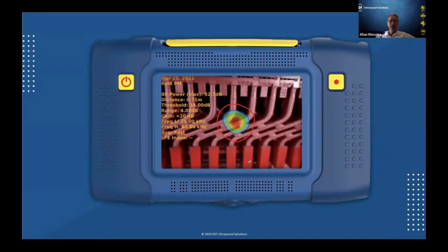There's a slide here that shows what the defect was. In behind there, they found a welding rod. During the rebuilding of this asset, one of the welders had carelessly discarded a welding rod, and it was caught in back, and it was bridging two electrodes.